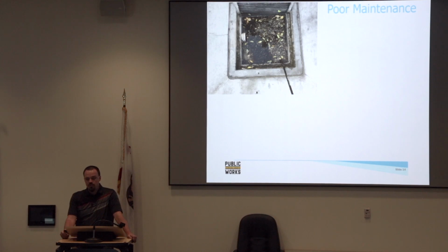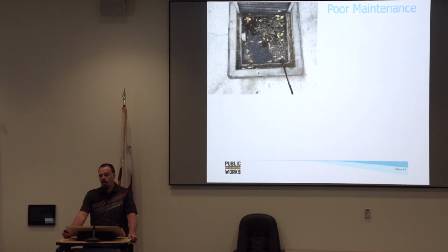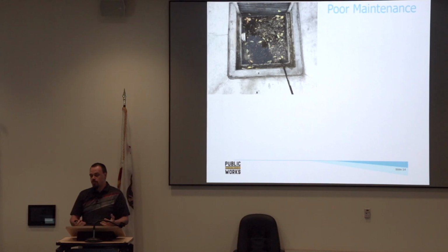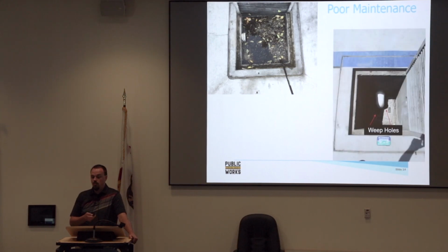This is the sedimentation manhole of a dry well system. So Troy had showed us earlier the Maxwell Plus from Torrent. That one has a sedimentation manhole, and then it goes into a bigger dry well where the actual infiltration takes place. In this case, we have standing water in the sedimentation manhole, which tells me the infiltration system is completely plugged. So this is what the sedimentation manholes typically look like.